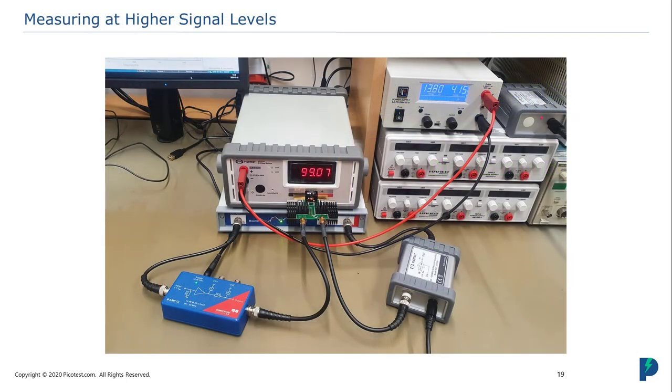Here's a nice clean setup picture showing an inductor being biased at 99 amps. There's a BAMP12 source power amplifier connected, so we can use larger AC signals to modulate the AC signal, so it's a larger signal. And you can see the ground isolator there. That's the J2113 connected to port 2. And you can see that the power supply, the external bench supply, is operating at about 4.15 amps to get 99 amps of bias current. So this is a nice, relatively portable measurement that can go all the way up to 125 amps.